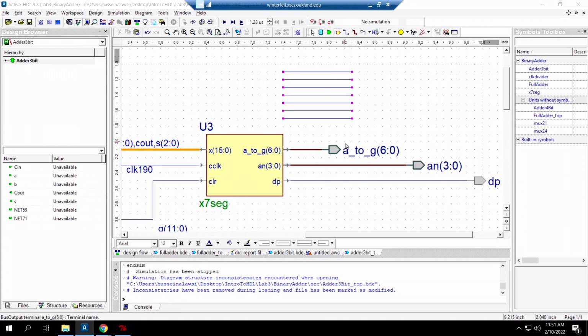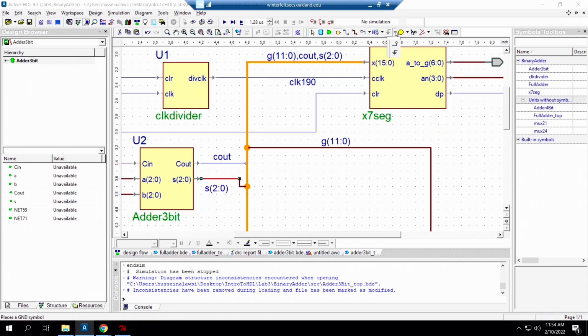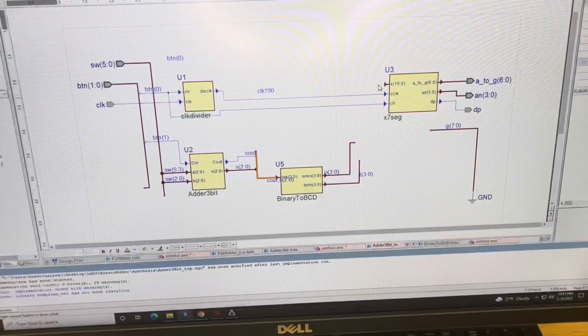Next thing I want to show you is where we place the ground from. So we go here, we click on this one, and then we choose the ground. Or we could just type the letter G on the keyboard and it will give us a ground. We could remove the extra that we don't need with the delete button. Or as you can see here, I just press G and it's attached to the mouse, and then I always need to move the cursor back.